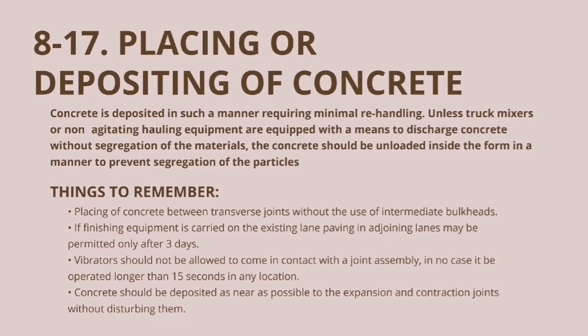Placing or depositing of concrete. Concrete is deposited in such a manner requiring minimal rehandling, unless truck mixers or non-agitating hauling equipment are equipped with a means of discharging concrete without segregation of the materials. The concrete should be unloaded inside the form in a manner to prevent segregation of the particles.